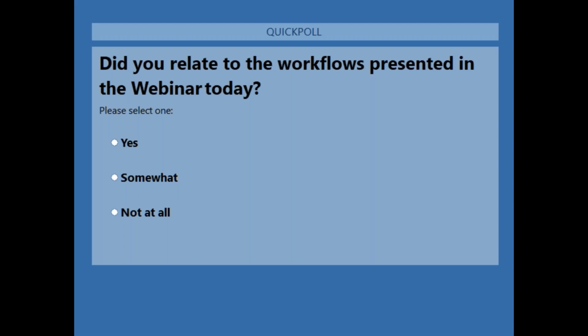Basically, the first question talks about the file being coordinated with Smart Plant 3D. The answer is, I was talking about Autodesk Plant Solution, but if you're more into the coordination and collaboration piece of it, you could take the VUE file which is coming from Smart Plant 3D, and there is a Smart Plant app which needs to be installed on top of Navisworks Manage, which can help you to do these coordinations.